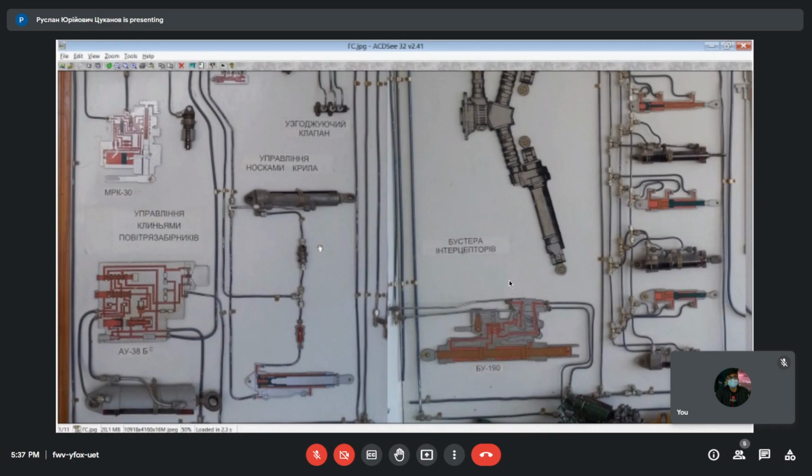Here, leading edge flaps. Leading edge flaps here are controlled independently from the flaps by a hydraulic actuator, one per each wing. So this is the real structure, which is in this picture. One actuator is placed in one wing. There are four sections of slots, but they are controlled by a single actuator.